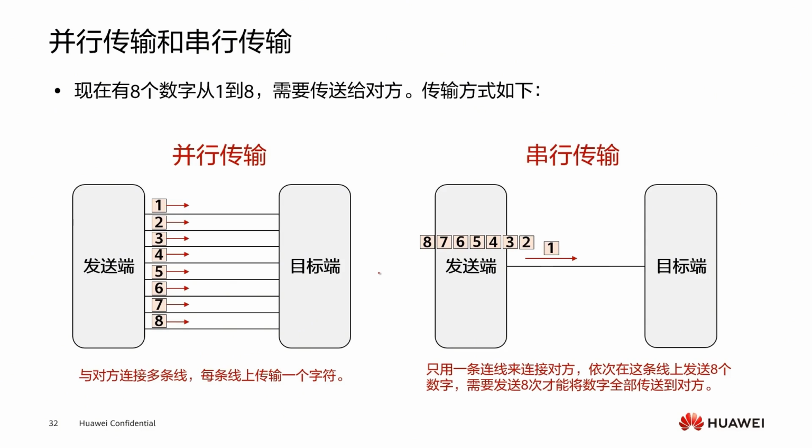In the transfer mode of the hard disk, it can be divided into parallel transfer and serial transfer. Parallel transfer has high transfer efficiency, but the transfer distance is not long. The transfer frequency is also not high. Using multiple lines for long-distance transmission is more expensive than using a single line, and it requires thicker wires to reduce signal attenuation, but bundling them into a single cable is quite difficult. Long-distance transmission is affected by wire resistance and other factors. The data of each line arrives at the other party at different times.